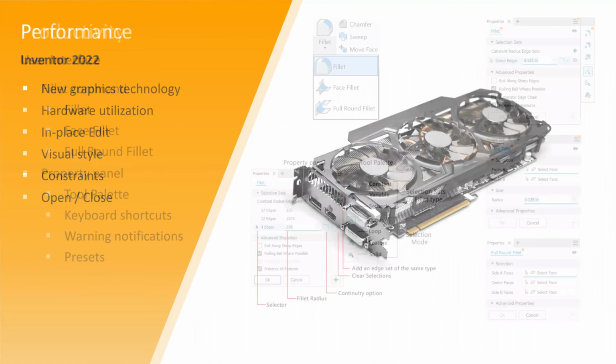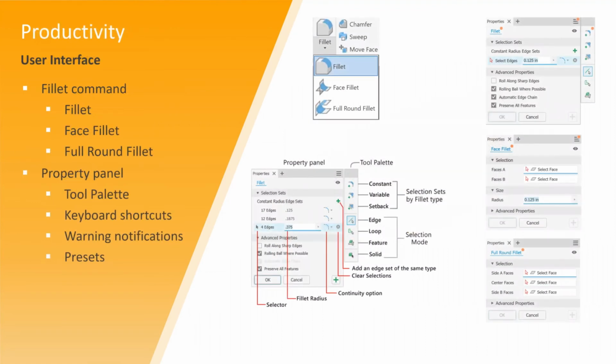Now, a number of little enhancements here just to dig down a little into some of the finer details. In the 2022 release, you'll notice a number of new dialogs. So previously the fillet dialog box, these have been changing over the last couple of releases, and we've now got some new functionality in the fillet dialog, which changes the way this behaves a little, in the sense of the little sub menu to the right of our properties panel for the fillets.